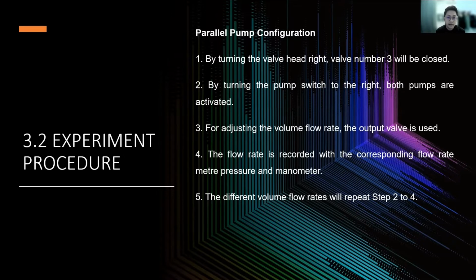So the first pump configuration is parallel. The procedure is, firstly, by turning the valve head right, valve number 3 will be closed. Second, by turning the pump switch to the right, both pumps are activated.